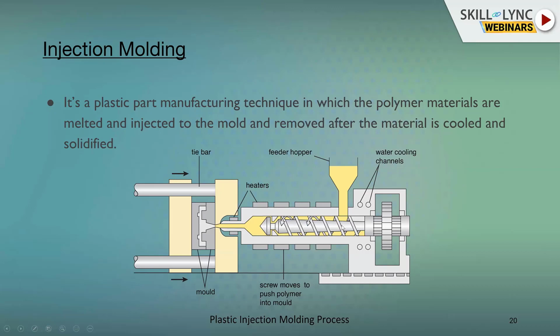utilizing the heat coming from the heating elements surrounding the screw system. The plastic material is then melted and injected into the clamping unit, which consists of the mold system, further divided into core and cavity. The core additionally has a moving mechanism which helps it move back and forth when the molten material is injected into the mold.